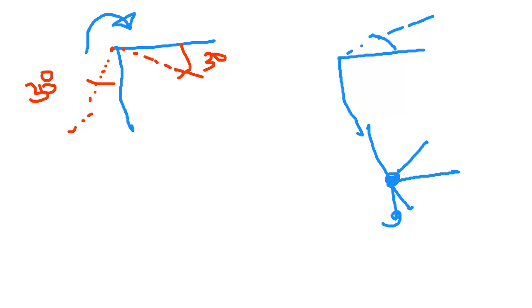So if this member is rotating, definitely this is going to be rotated. But remember, if this is rigidly fixed, definitely this rotation will be induced on this member, but it will subside to the other. It will try to not rotate here because this is 0°. That is the beauty of a rigid joint. So this joint, if it is rotated and this is rigidly fixed, this will only affect this joint. Are you able to understand this or not?